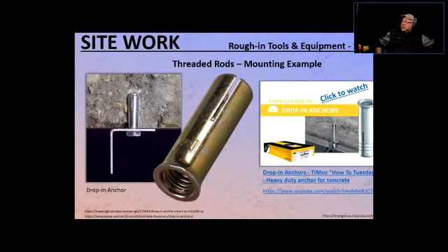What happens? You can see there's a bit of a slit here. It's a cut. So you drill the appropriate size of hole that the specific anchor calls for. Of course, this would be drilling the hole with the hammer drill. And sometimes it's going to be a heavier hammer drill, because if you have to drill a lot of them, that may be half inch or maybe bigger anchors, if you just use a regular hammer drill, you are going to get tired pretty quickly.